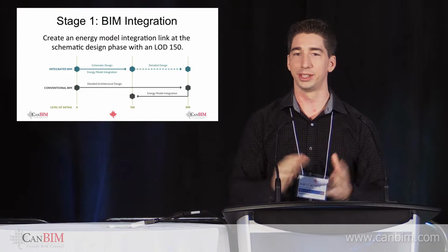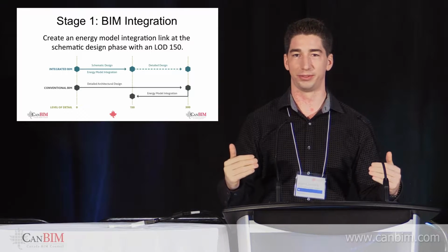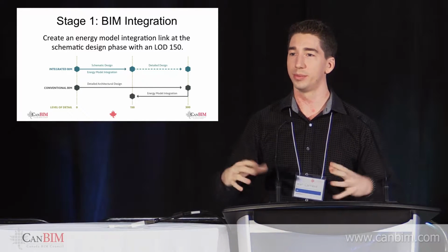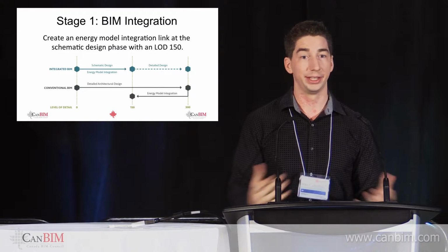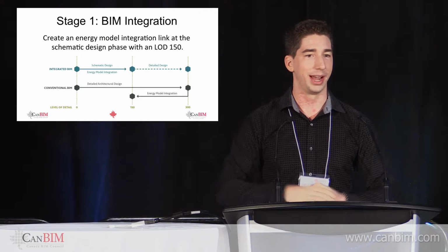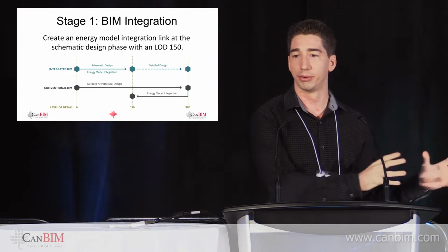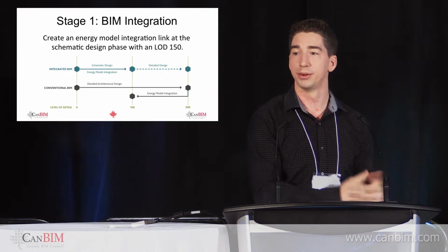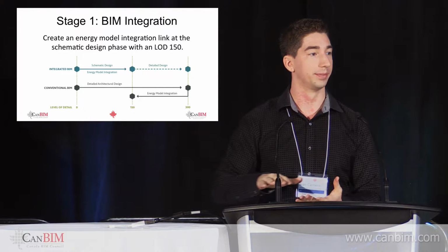So it takes a little bit of fixing, a little bit of processing work, but I have to go from level 300 down to 150. And I've got to do that in a way that doesn't compromise your model, but captures the essence of what is actually there. If you've got 500,000 square feet of building, in a few hours, I can get that entire model integrated into our energy analysis software. I can start running loads with a few more hours, and I can give it back to you. And I can exchange all that information back through your model.